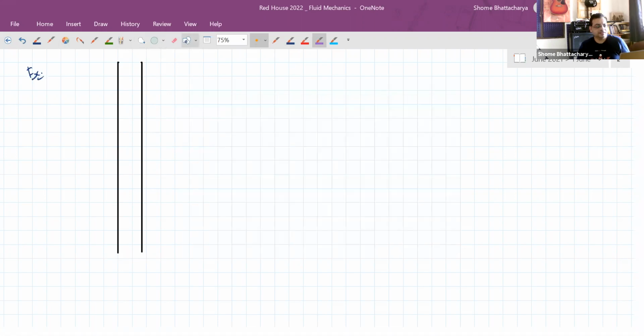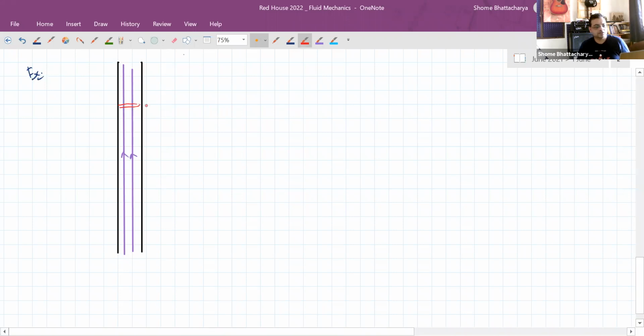Okay. The pressure difference in such a situation will be the same as the pressure difference would have been in a static column of liquid. That is, 2 points separated by a vertical height of h will again have a pressure difference of rho gh. And it's not entirely surprising when you think in terms of work energy also, why that's going to happen. So firstly, you can see here that area of cross section is uniform. So velocity of flow will also be same.